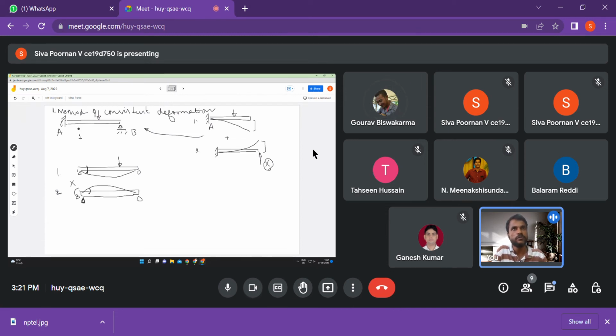Okay, so removing one of the support forces, here we are removing the moment, here we are removing the propped support reaction, right? That will not make it unstable. If we remove two, then it will become unstable. So this is still a stable system, therefore we can treat this also as simply supported and solve it, or we can do it as a cantilever also. So you can do it any way.